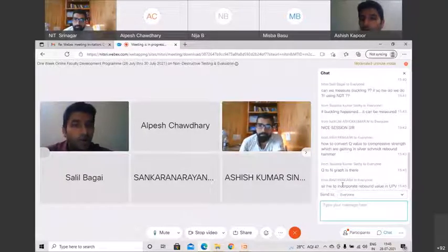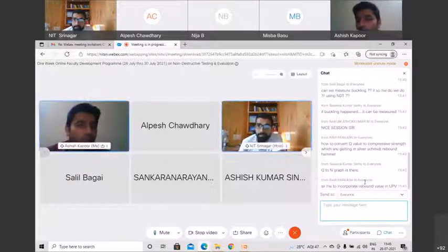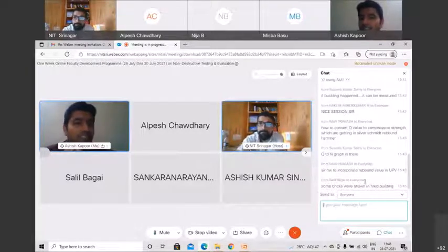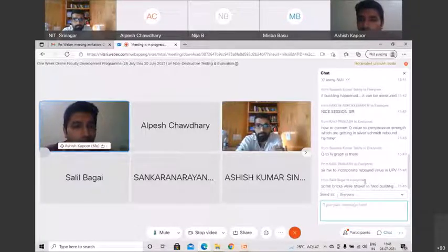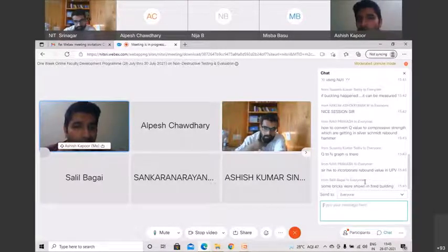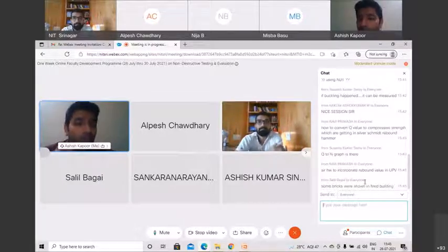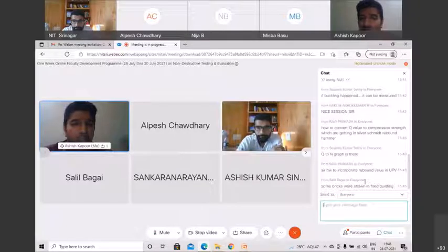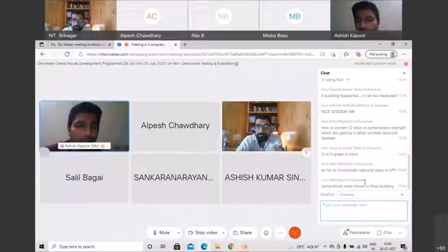Sir, one more question. How to incorporate rebound value in UPV? There is an option given in your UPV machine, whether you are using Pundit Lab or Pundit Lab Plus, which is mentioned in your instrument, that you have to enter the rebound value. After entering the rebound value, you will get a combined result based on the rebound value as well as ultrasonic pulse velocity, and you will get the strength, or you can call it the grade of concrete.